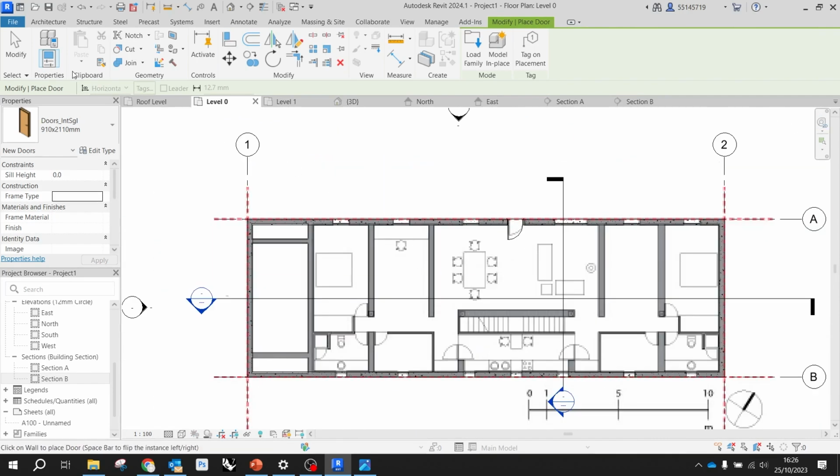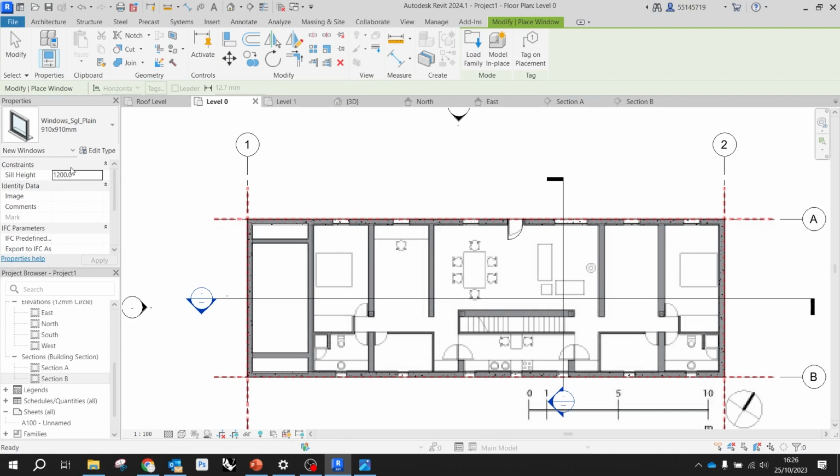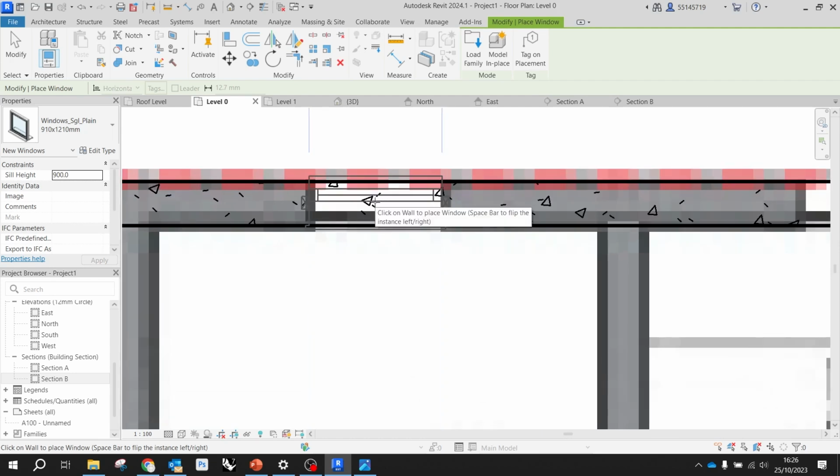And we're gonna do the same, exactly the same with windows, okay? So go to Windows. Let's start with a standard measure. Let's check the second one maybe. And you see that I'm basically hovering on top of the wall where the window is supposed to sit. And depending on how close or far I'm from the exteriors, right? The window will basically pick up what's going to be the direction of the glazed portion, right? It's going to be more towards the interiors or more towards the exteriors.